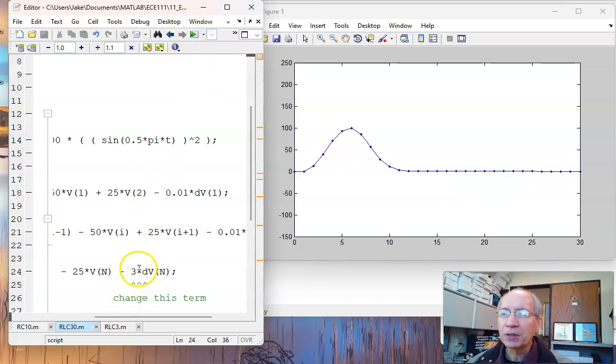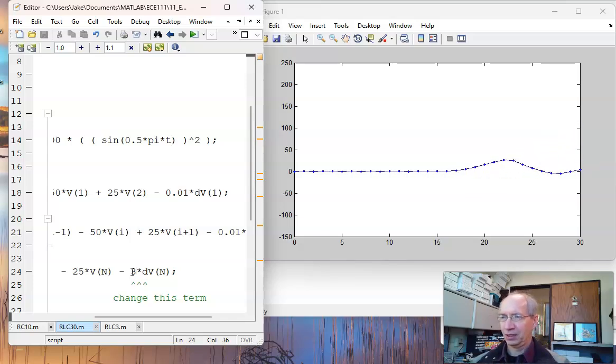You can actually calculate what this number should be. When you take electromagnetics, you'll calculate that. Here, using MATLAB, I'm just going to use trial and error to find it. At 3, that's pretty good. That's still a slightly plus reflection, so 3 is a little bit too small. Let's try 7. Wave goes down to the right, hits the right endpoint. Slightly negative. Okay, let's try 6.